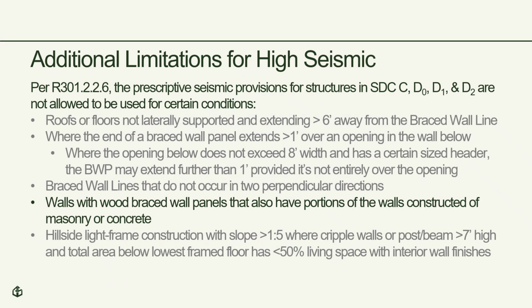The fourth additional limitation for high seismic is where you have walls where there are wood brace wall panels and a portion of the wall is constructed of masonry or concrete.